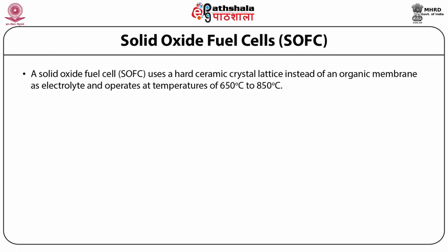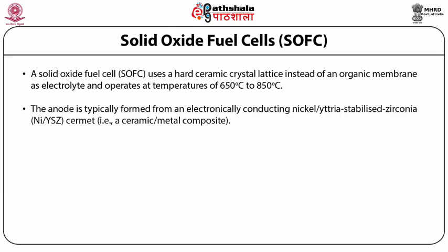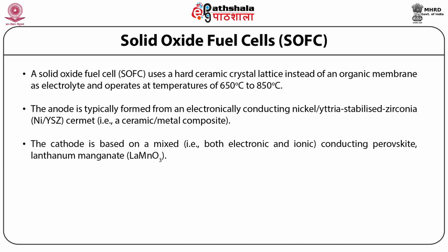Today's technology employs several ceramic materials as the active SOFC components. The anode is typically formed from an electronic conducting nickel yttria stabilized zirconia cermet, that is a ceramic or metal composite. The cathode is based on a mixed electronic and ionic conducting perovskite, lanthanum manganite.